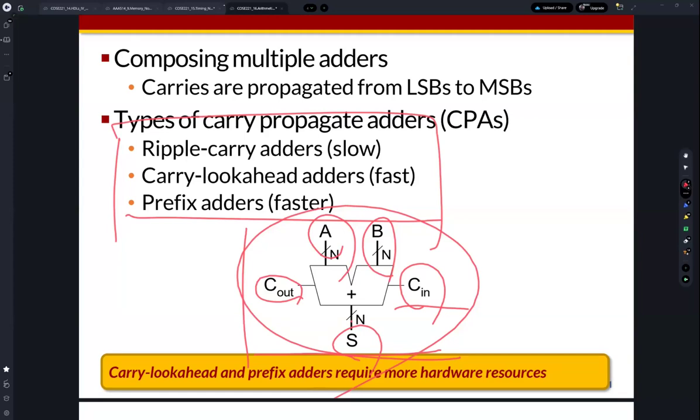We learned about the timing, right? Performance is usually proportional to the clock frequency. In order to increase the clock frequency, we need to reduce the clock period, TC. How? The minimum clock period is determined by the setup constraint.